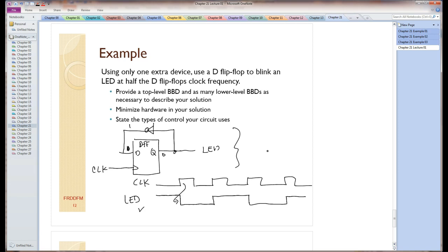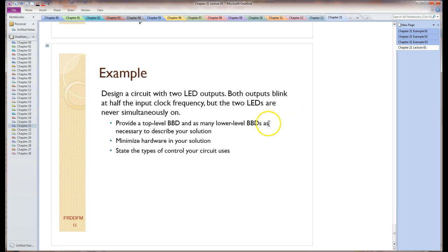It uses a D flip-flop to cut the clock frequency in half. Remember this, it comes up a lot. Certainly it's a good test interview question. The issue is that people expect you to know that, and it's a simple idea. Sometimes it's hard to derive, but if you kind of have an idea where you're going with it, it works.